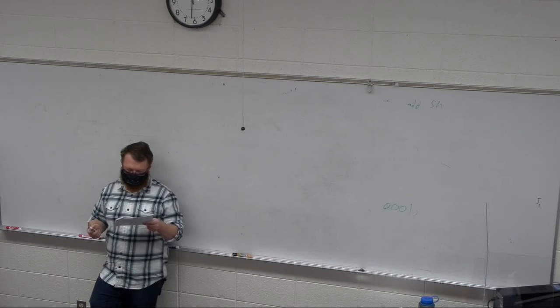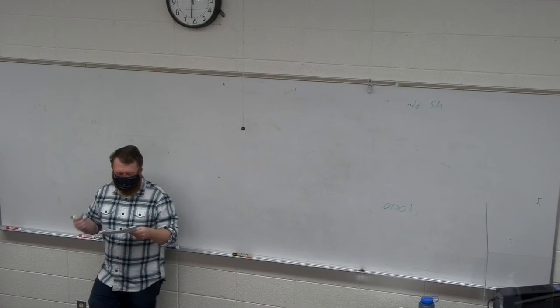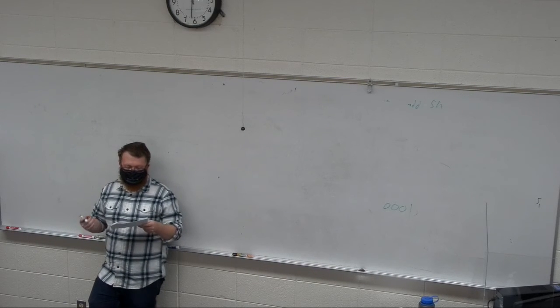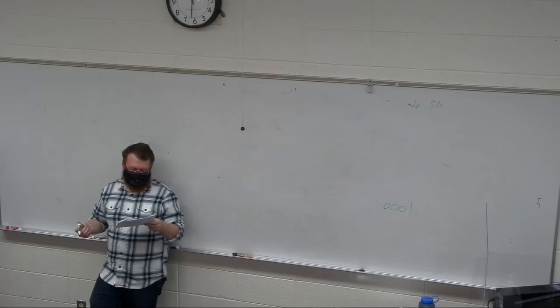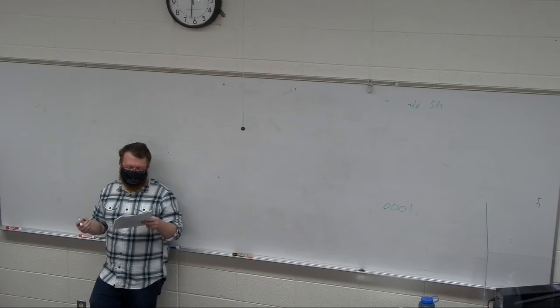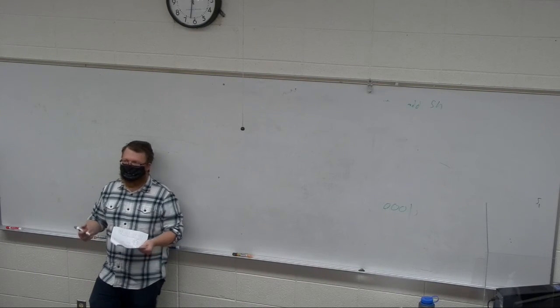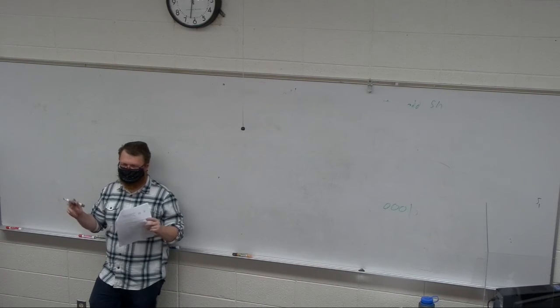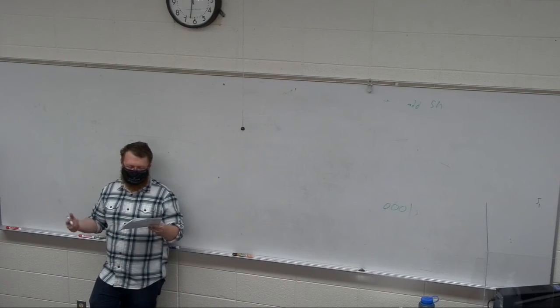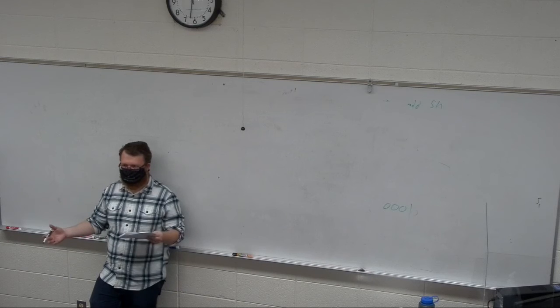8 was a really mixed results one, which is okay. The first one is a NOR gate. And that's because if you look at it, if either A or B is true, it has to get pulled to 0, right? Because those switches turn on and pull it to 0. The one thing you can always count on is ground will always win. There is no supply that is going to outsupply ground, in general, in circuits until you get to high power stuff. But for most of your circuits, assume that nothing is going to beat out ground. And so if A or B connects Y, the output, to ground, you have your truth table right there,